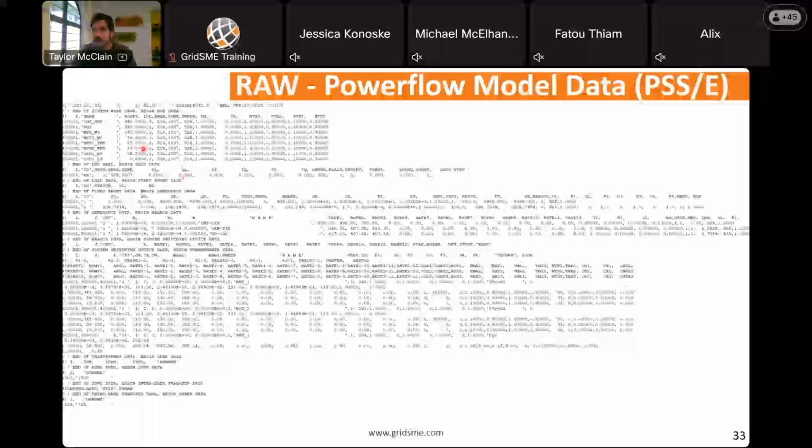But it's all the same sort of information. You have your POI, MPT, high voltage, medium voltage. This has 3 winding transformers, so there's tertiary buses, and your medium voltage and your low voltage. So regardless of what software you're working in, these types of files here define the steady state or the power flow portion.